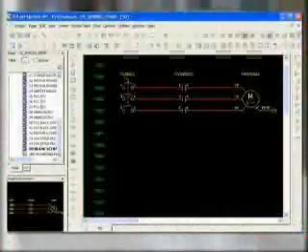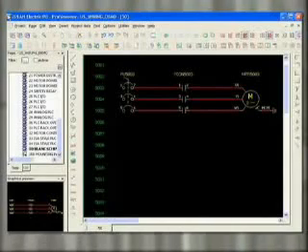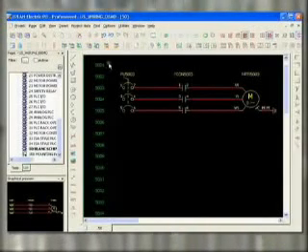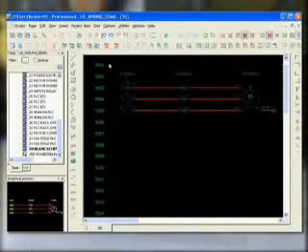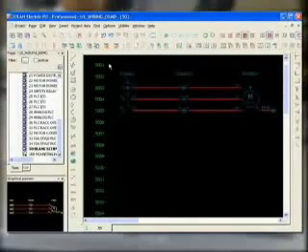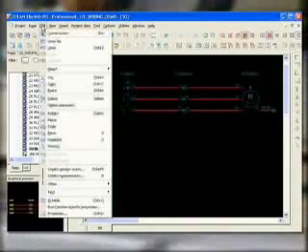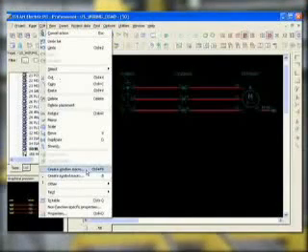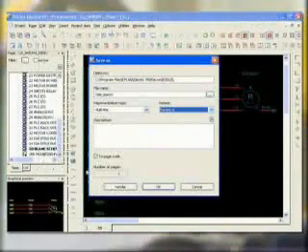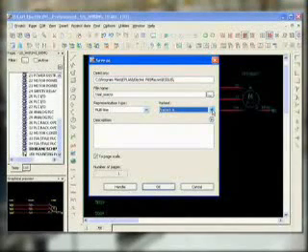One of the most powerful features of Eplan Electric P8 is the macro variant technology. Macros allow you to standardize schematics between projects. Macro variant technology allows you to save up to 8 different variations of a section of schematic out to a single file. To create a macro, select the section of schematic you'd like to use and select Create Window Macro. Here, you can name the macro and choose the variant.